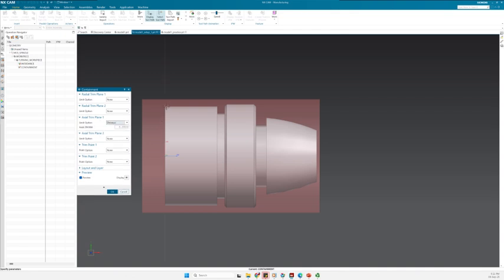If the distance is 0, it is supposed that the spindle will be here. So you have this much space for spindle clamping, which is fine. But then again, it's a little bit too much in that you cannot finally create your part because there would be collision here.